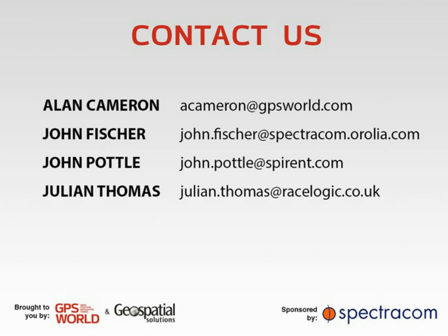We've observed that there's kind of two classes of multi-GNSS, multi-constellation receivers. One is where they'll do one constellation at a time. So that's more of a simple case. So even though they do multiple systems, they'll only do one at any particular time. And then the other class are the ones that are using satellites from all the different constellations and trying to do a more composite navigation solution. It's, again, much more difficult to do, much larger matrices, but can have some real advantages.